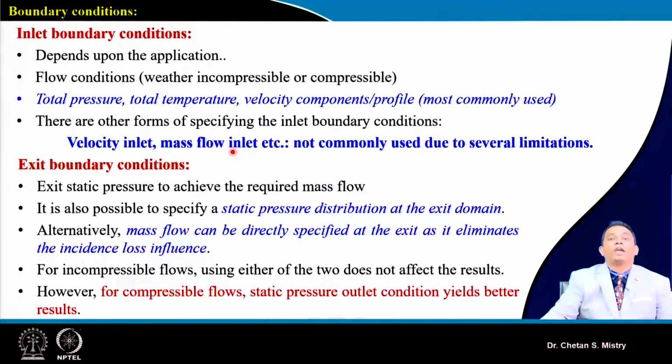With that we will have the distribution of inlet pressure. Suppose we have used a multi-hole probe to measure the inlet velocities before the rotor or stator. That velocity profile can also be taken as an inlet boundary condition.